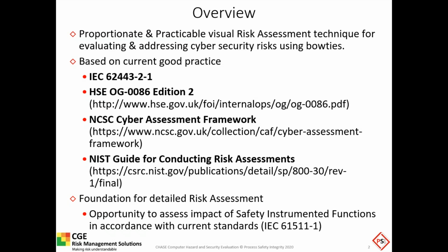And we're using this to ensure that electronic and programmable electronic threats are properly understood across all the stakeholders, not just the IT specialists or the operational technology specialists. And one of the key drivers is the second edition of the Functional Safety Standard 61511 now requires you to do a security risk assessment. So we believe this technique will help to address that requirement, to better understand the relationship between the bits and the bytes in your control system and the pipes and the pumps on your plant.